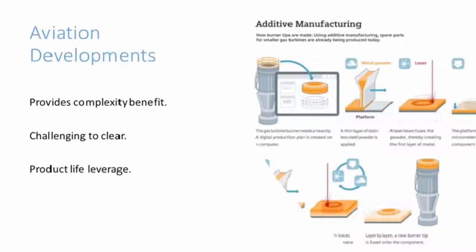The ability to create complex parts using techniques not previously available will remain the main aviation application in the short to medium term. ALM will be used for alloys, precious metals, and for products in which different sections are printed with different materials. Such products could include a material that provides heat resistance and another for ensuring stability. Moreover, metals that melt at high temperatures could be used in completely new ways.